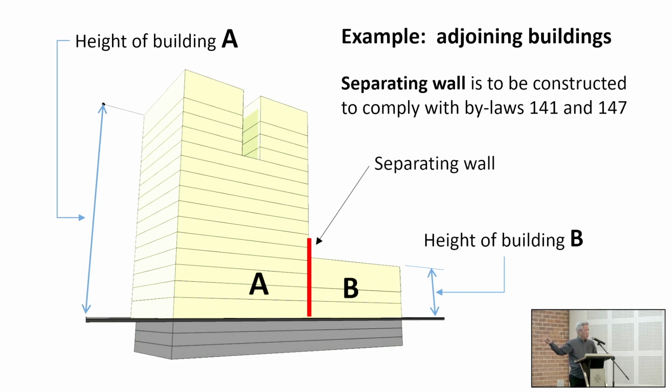Turning into a party wall means what? I have to cut off all the services that are crossing the wall, right? Then you have to apply the construction of a party wall. So you have to break up everything. In this building, you have to start reinstalling all your fire services again, all your water supply and electrical supply and everything, and turn that into a party wall, which is a physical separation of all the systems. Yeah? Okay, I hope I've made that clear in terms of the definition.